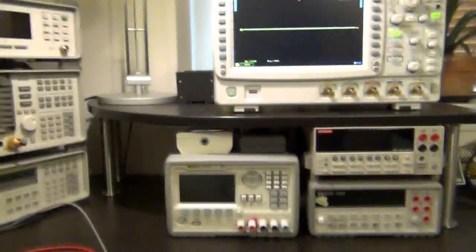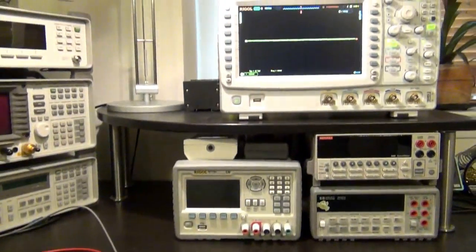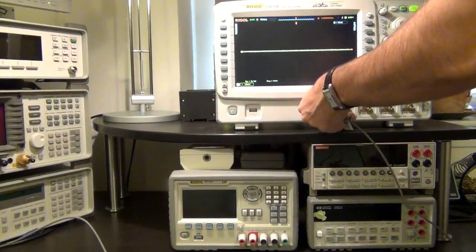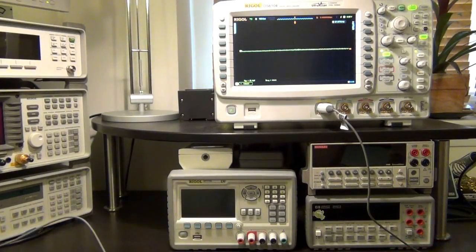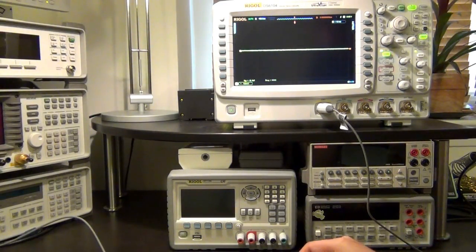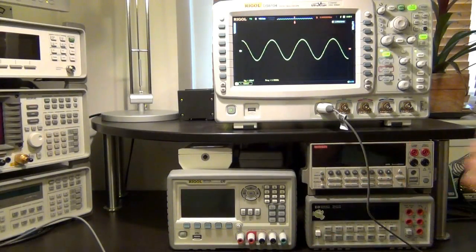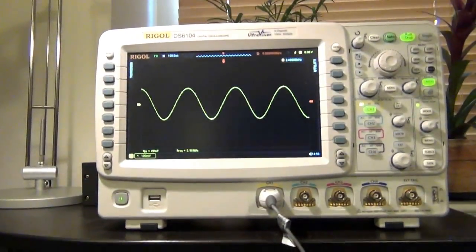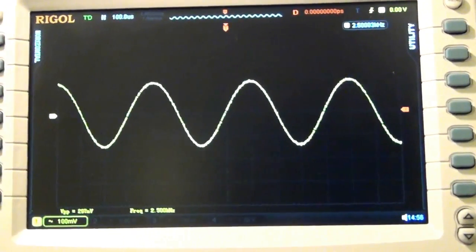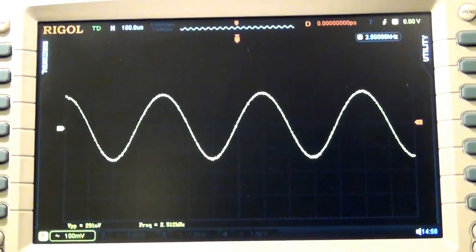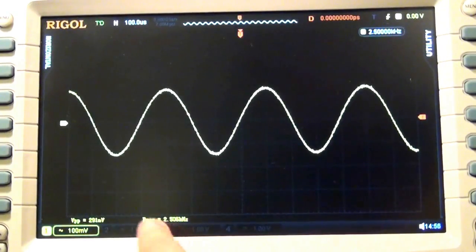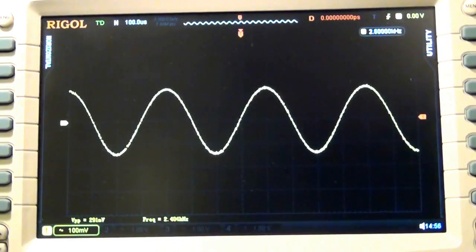Now we can just back up a little bit. Here's the circuit, here's the oscilloscope. We'll connect this up. There we go. And I will look at the output of just the first stage. There it is. Now let's see if this makes sense. I am applying a 2.5 kilohertz signal, so let's look at the oscilloscope more carefully. What am I seeing? I'm seeing a sinusoid that has a frequency, I'm measuring it here, 2.5 kilohertz. It also shows up here at the top in the frequency counter.